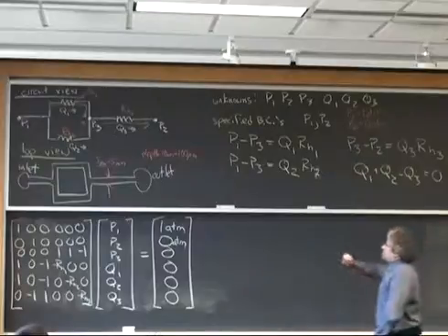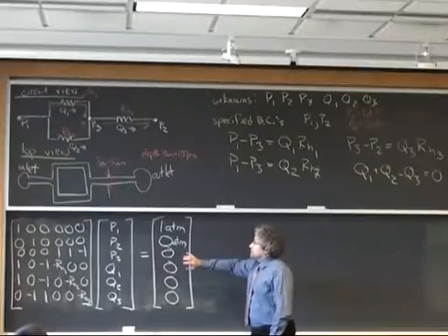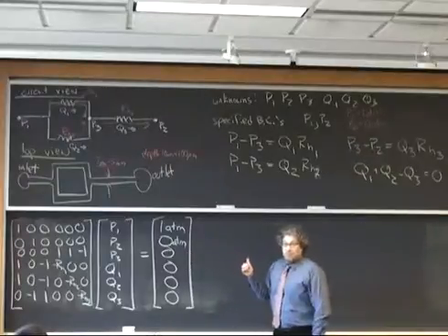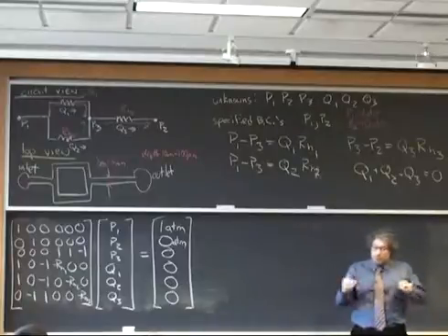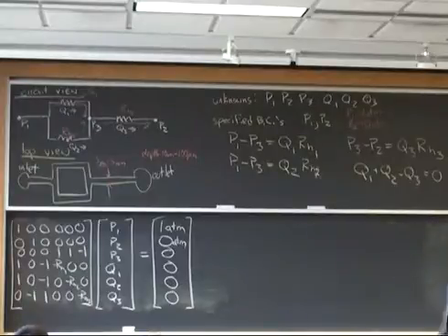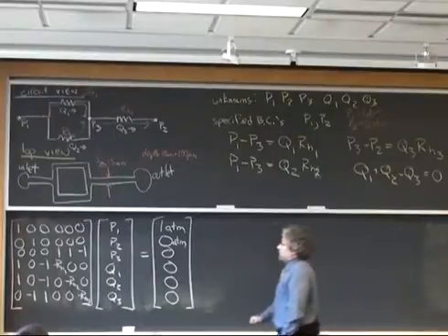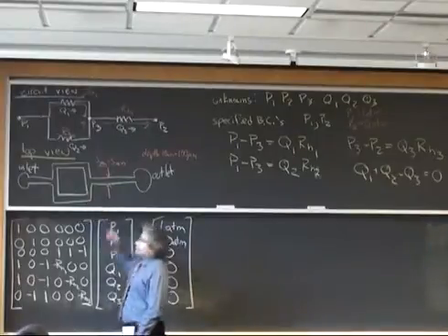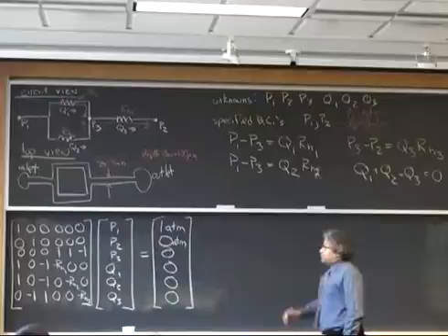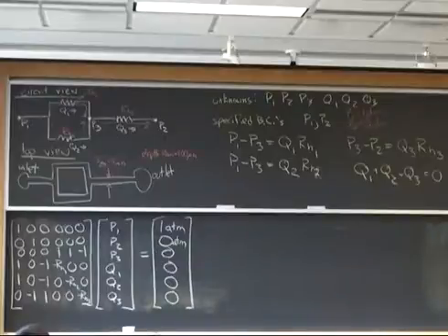Now, this Hagen-Poiseuille law, which we're applying here, is only correct in a number of limits. We needed to have unidirectional flow. The tubes needed to be long. We needed to basically assume that the effects of the edges or of the nodes was relatively small. But oftentimes, this is a perfectly reasonable approximation in these microscale systems.